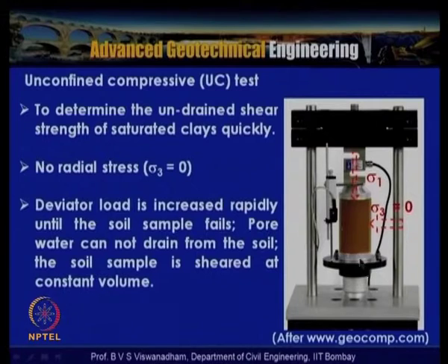So this is a quick test which can give the undrained shear strength of a saturated sample. Sometimes this is also used for partially saturated soils, basically to get the unconfined compressive strength of a sample, and afterwards you can get the undrained cohesion. The sample need not be completely saturated, but truly speaking it should be, to determine the undrained shear strength of a saturated clay quickly.